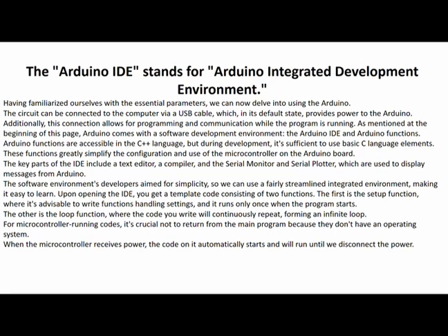The other is the loop function, where the code written will continuously loop, forming an infinite cycle. For microcontroller running codes, it's crucial not to return from the main program since they don't have an operating system. When the microcontroller receives power, the code on it automatically starts and will run until we disconnect the power.